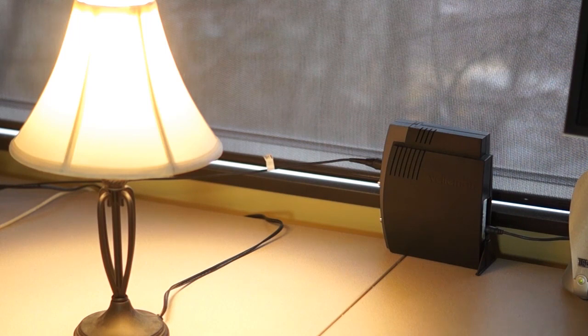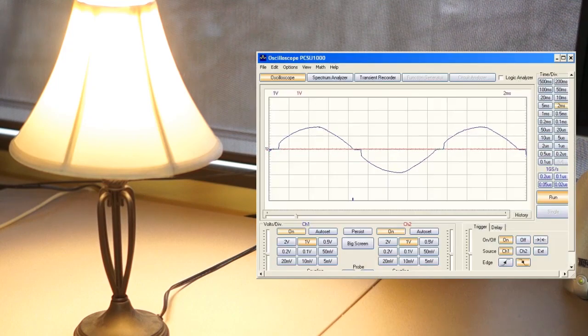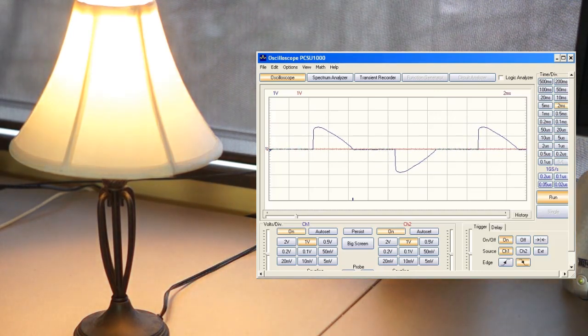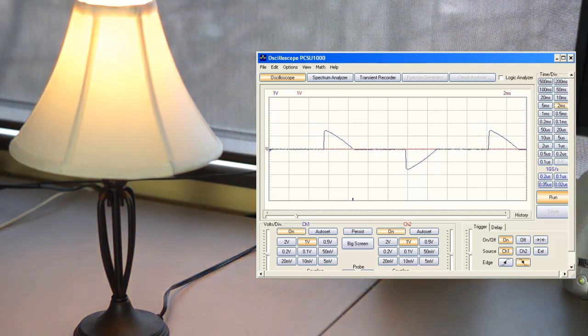We will now demonstrate in real time the operation of a typical dimmer. Our setup is this. The output of the dimmer is connected to the light you see here. And additionally, an oscilloscope is displaying the dimmer output voltage. We will now initiate a gradual fade off. Watch the change in the voltage waveform as the light fades. Notice that as the delay time increases, the light output decreases because less power is being applied.